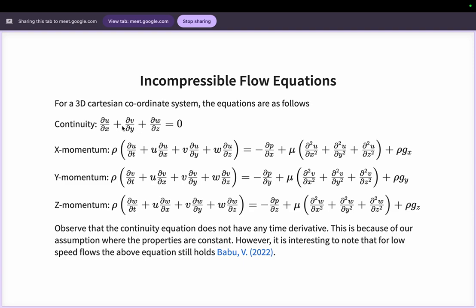And the most interesting thing here is in incompressible flows. For these particular equations, though I stated that you have constant properties throughout, that is an assumption we have taken. So that is one reason why you do not have any unsteady term in the continuity equation, but that is not always the case. You can still have variable properties, as in natural convection, for example. When you take a natural convection example, density is a property that will be continuously varying, because otherwise there is no natural convection or buoyancy forces.